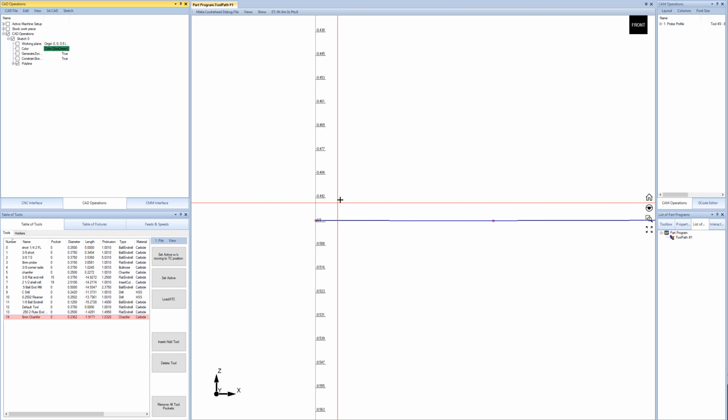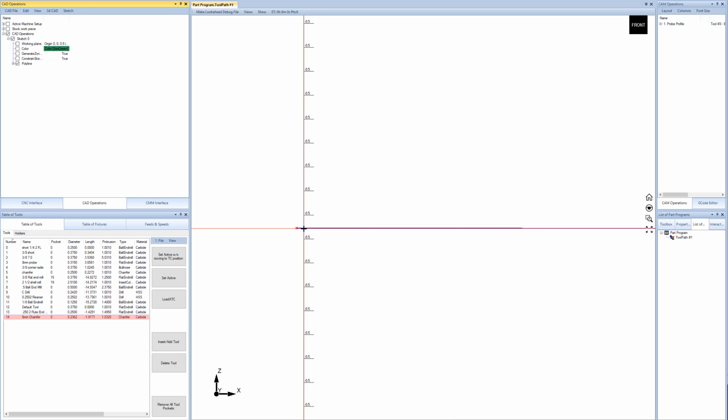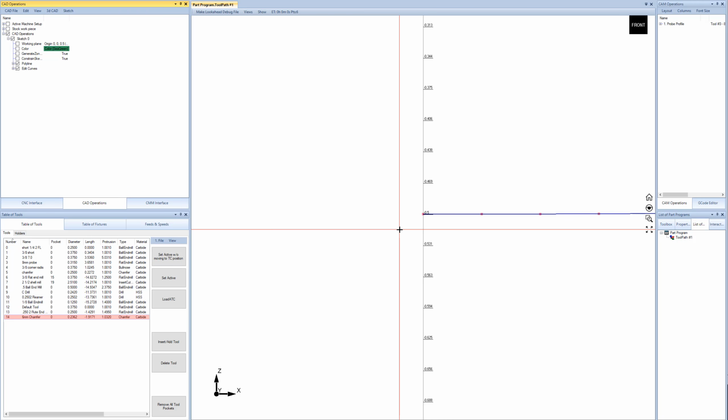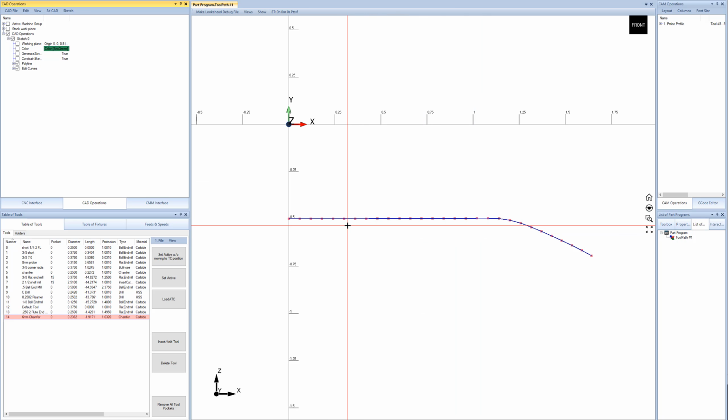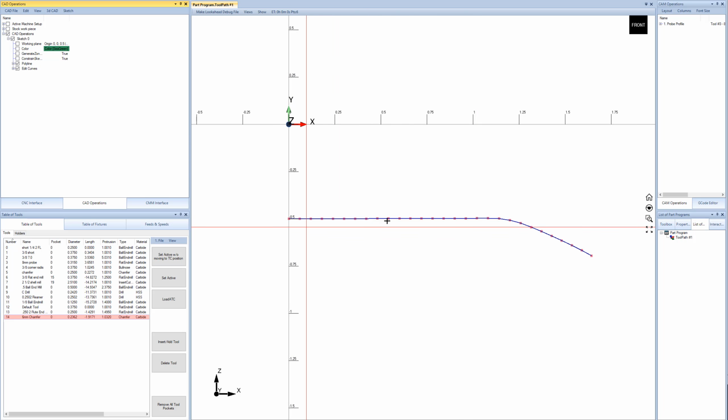So the first thing we can see here is, I've gone through this a couple times now, I can see that this first point is just barely over the center, our origin there in the X direction. So I'm just going to take this point and move it over just a little bit, just so that it's not past the center. And that's going to be really important later. Basically, we can't do what's called a surface of revolution if we have data crossing over the point where we revolve around. So just note that kind of thing is important.